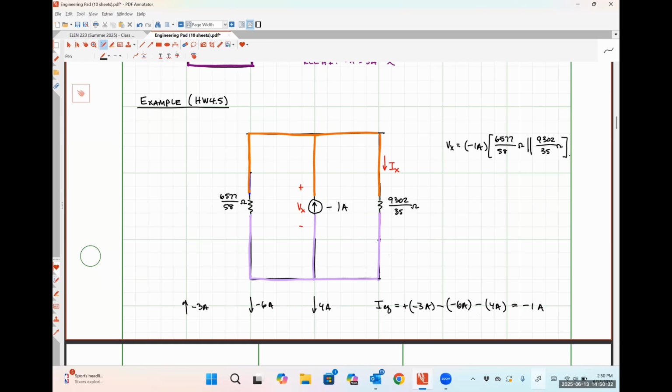there with the two parallel lines in the middle just means the resistance on the left is in parallel with the resistance on the right. Okay. So with these big ugly fractions, I just didn't want to wind up writing it all out. And for what it's worth, actually, I believe I'm missing a negative sign. The reason why I'm saying that is because this current is flowing into the negative polarity terminal, so I should put an extra minus sign out front there.